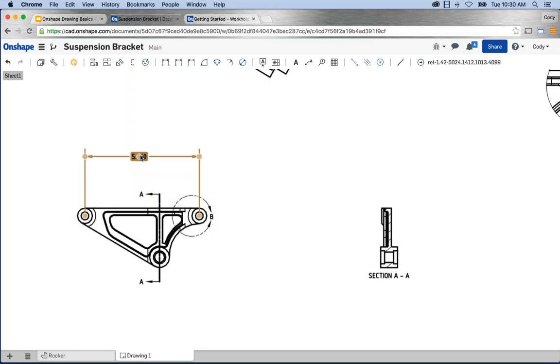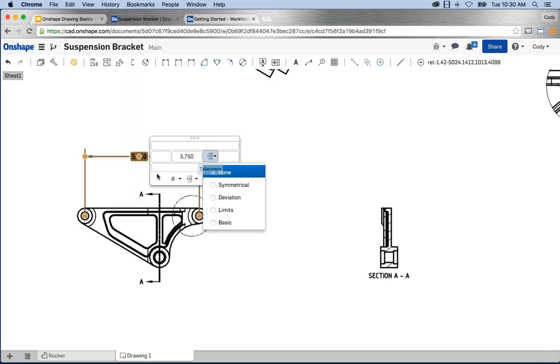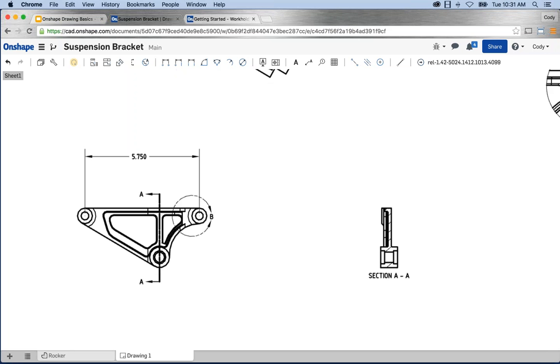Another commonly asked question is, what if I wanted to change the tolerance, for example, or what if I wanted to add a note to this dimension? And this is a big one. If you left-click a dimension on the actual text, you'll see a little dialog appears just next to your cursor. If you move your cursor over that dialog, a flyout pops out where you can enter text, you can change the tolerance, you can add symbols, so you can do all kinds of neat things in this dimension properties dialog. But definitely worth pointing out, the key thing with it, again, left-click the dimension, move your cursor over that little dialog, and it flies out.